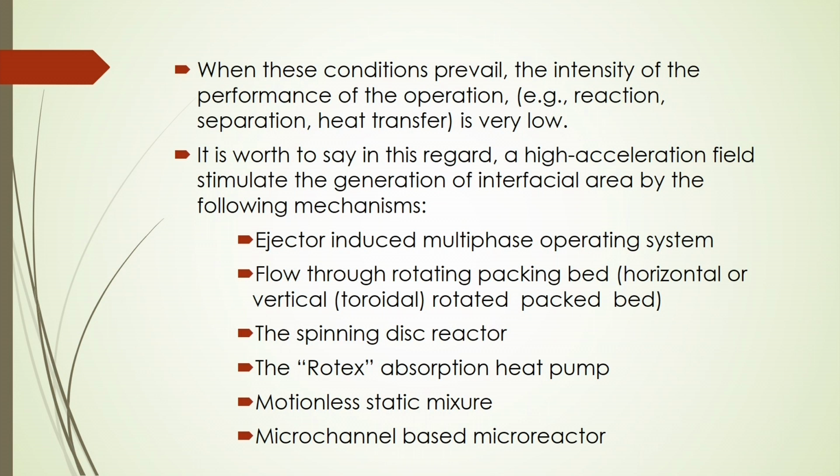So, in that case you may get more residence time of the gases in the liquid, so that through the interface of those phases there will be a transfer of some components from one phase to another phase. So, this is the mechanism of the ejector induced multiphase operating system, by which you can create that interfacial area, and its application for different chemical engineering processes. Just simply, gas absorption may happen here, even sometimes liquid extraction you can do here. So, this is one mechanism.